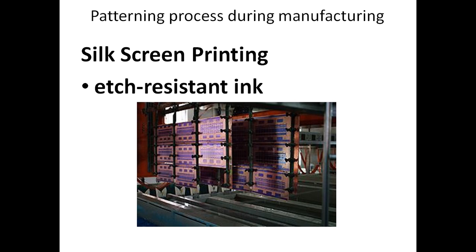Manufacturing a microstrip or microstrip patterns only on a substrate can be categorized as simple. For large volume of production, two simple techniques apply the concept of subtractive process, which means removing copper from an entirely copper-coated board, leaving only the desired pattern.